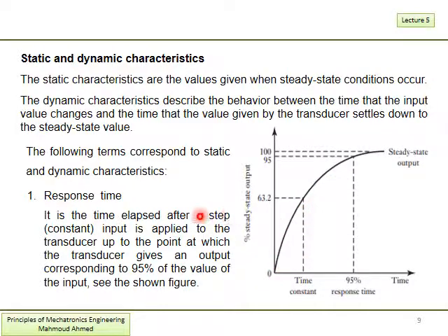First one is response time. What is response time? Response time is simply the time elapsed after a step input. It means we apply a constant input and see how the system responds to it. As shown here, for a step input, it takes this complete time to reach a steady state.